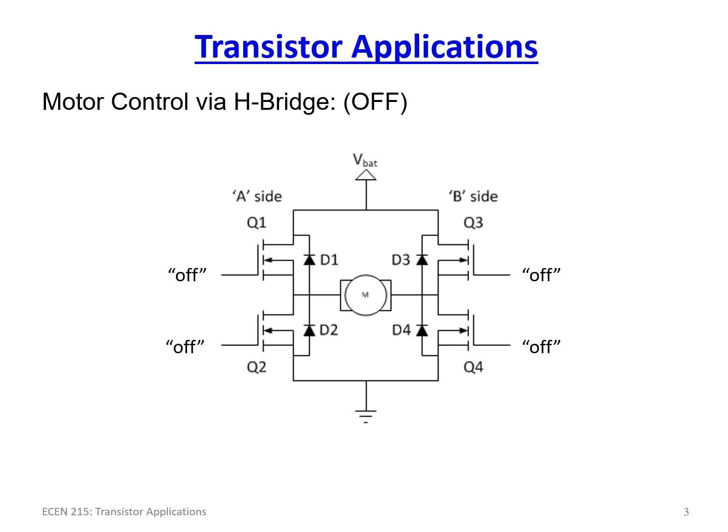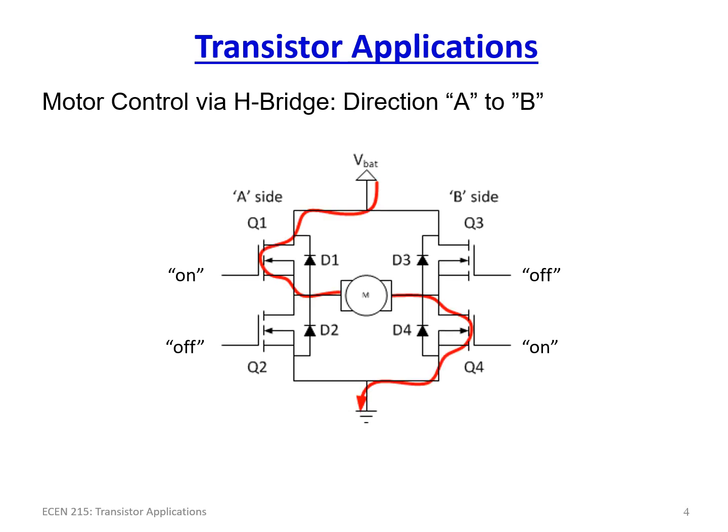However, what if I do want the motor to actually turn? And I want, in this case, the motor to turn in a clockwise direction. As we were saying a moment ago, let's say this is the positive and this is the negative side of the motor, and with the current going this way, the motor is going to turn clockwise. If that's my goal, then we turn on this transistor and the counter transistor across the H bridge, and we're going to see why we call it that in a minute.